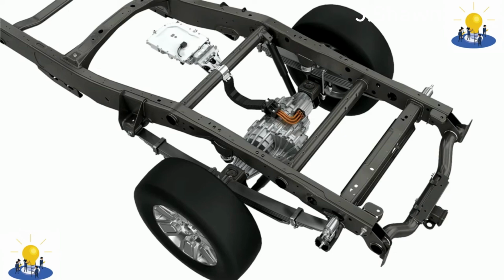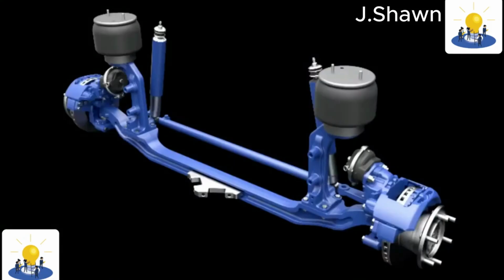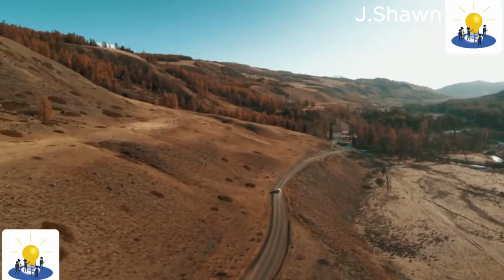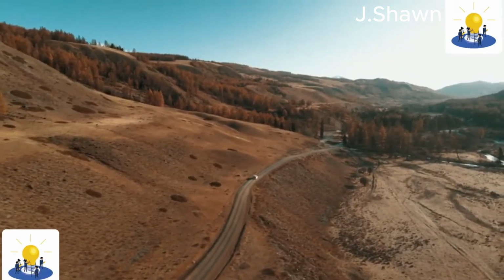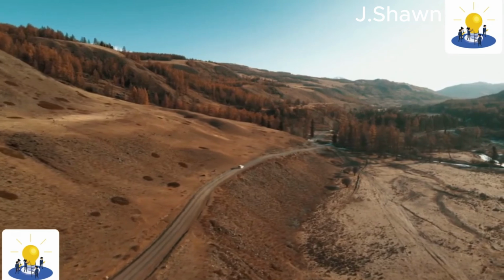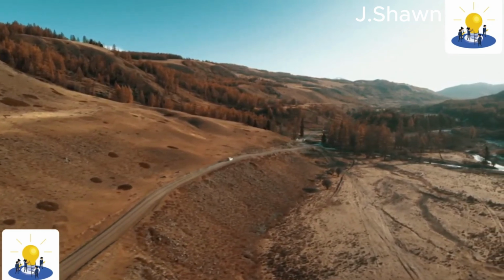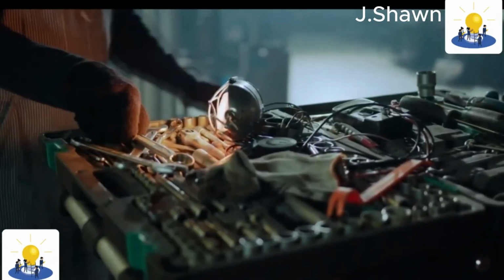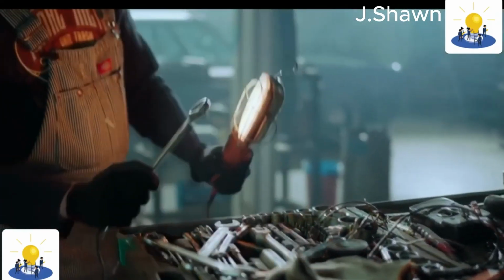Advantages: a beam axle is typically simple in design, rugged, and inexpensive to manufacture. Only one universal joint or constant velocity joint is needed at each steered and driven drive wheel, and none are needed at non-steered wheels. This reduces maintenance requirements and manufacturing costs compared to independent suspensions, which typically require two such joints at each driven wheel.